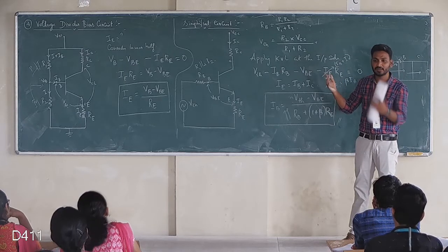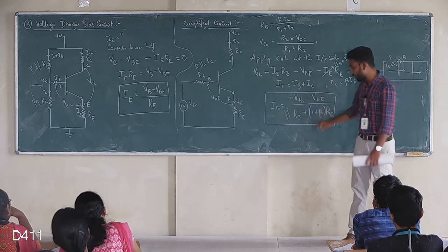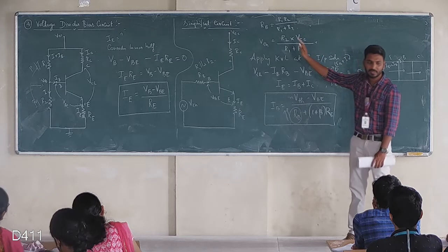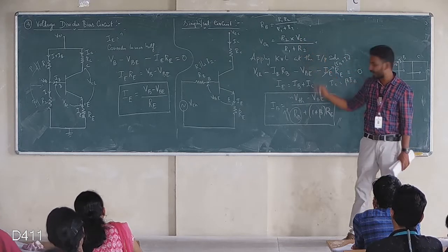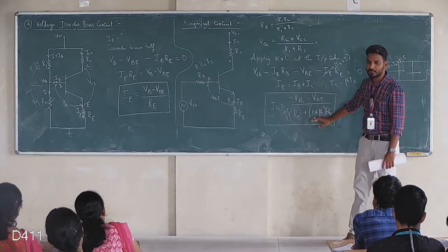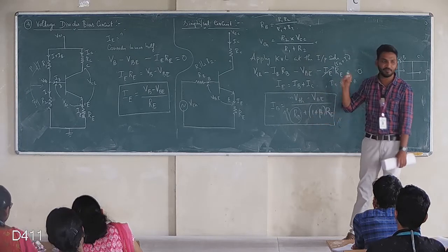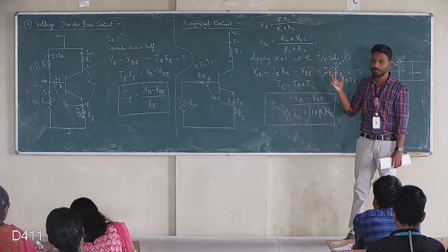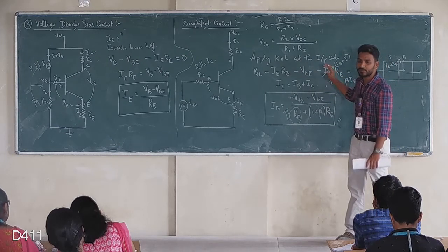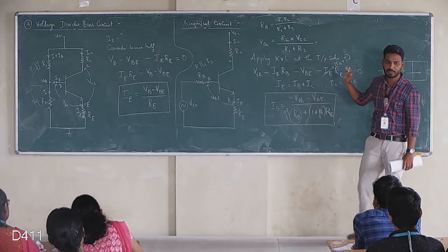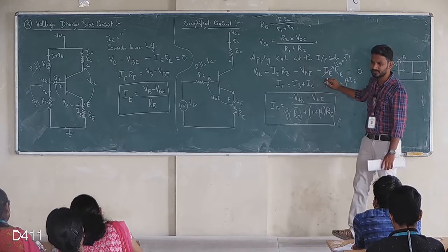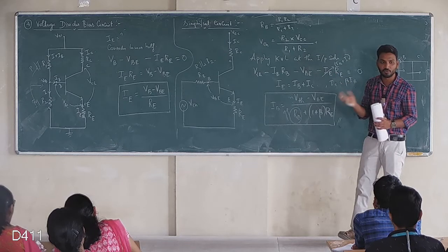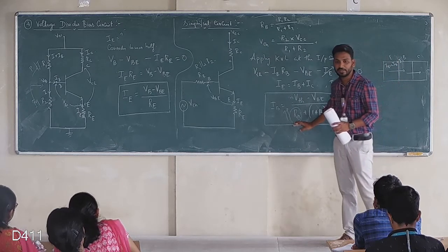In the other three circuits, we cannot change the value of beta. But in the voltage divider circuit, by fixing the value of RB, which is nothing but R1 and R2, and by properly selecting the R1 and R2 values, we can make the circuit independent of beta. So in this circuit, beta won't matter, and the Q point will be fixed constantly. Stability is very high compared to the other three bias circuits. So practically we use only voltage divider bias circuits. The Q point will be fixed at this point for the entire session. It won't shift upward or downward. So that is the advantage of the voltage divider bias circuit. Clear?